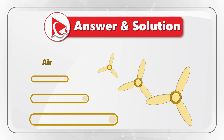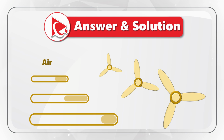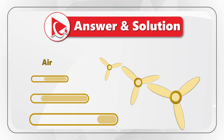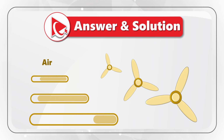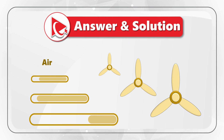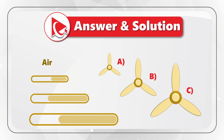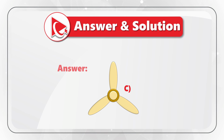In addition, the rotational speed of the fan affects the airflow rate. A higher RPM generally results in a higher airflow rate as the fan blades are able to move through the air at a faster rate. As you can see here, fans A, B, and C all have the same design. Given that the 3 fans have the same design but different sizes, the fan with the largest size will throw more air compared to the smaller fans. This is why the correct answer here is choice C.